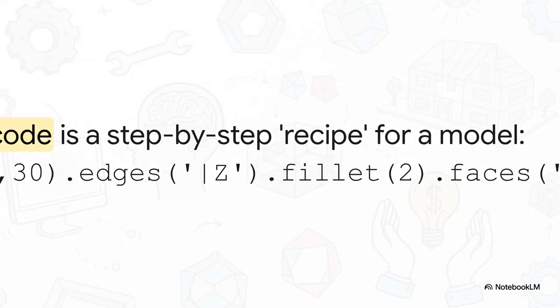And right here, you can see that whole recipe idea in action. This is a language called CadQuery, and you don't need to be a coder to get the logic. Each line is just a clear instruction. You start a new design, you draw a box with specific dimensions, you find the vertical edges to round them off, and then you find the top face and drill a hole. It's just a logical, step-by-step construction that's perfectly repeatable every single time.